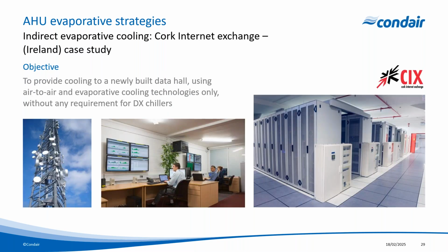So let's look at a case study that utilizes an indirect evaporative cooling strategy. This project is the Cork Internet Exchange in Ireland, and the objective here was to provide cooling to a newly built data hall using air-to-air and evaporative cooling technologies only. They did not want to use any DX expansion cooling systems, so no chillers or mechanical cooling in this type of system. So we worked with a leading air handler unit manufacturer to supply the evaporative systems for this project.